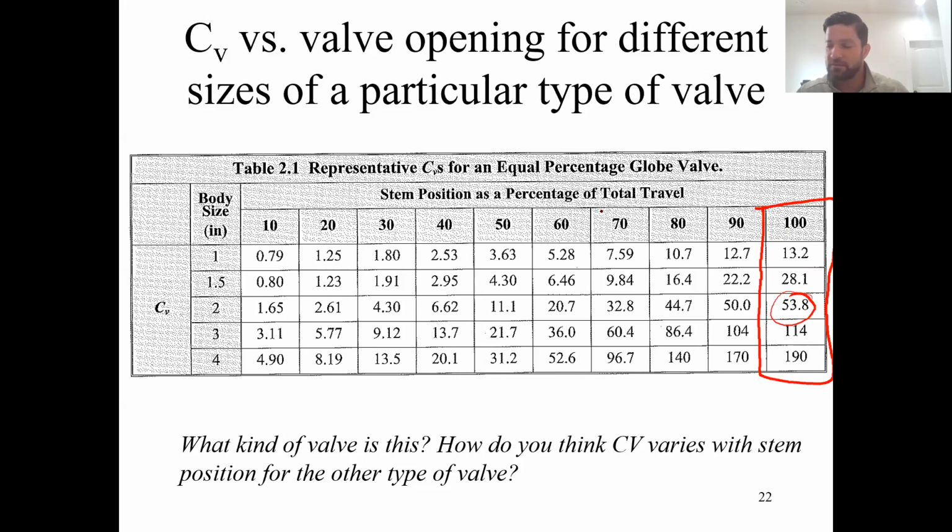A vendor might tell you this is the maximum value for the linear valve, but you don't have to give this information in here because you just take the ratio. But again, for this class, if you want to use a linear valve, just use this table and use CV max here to determine what that is.